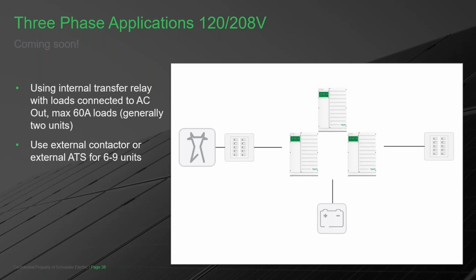So you see master of phase A, master of phase B, and master of phase C. This will keep these inverters at 120 degrees. So they're 120 volts each, and they are 120 degrees from each other. With the difference with 120-240, where the 2 phases, L1 and L2, are 180 degrees from each other, in a 3-phase, the phases are 120. And they'll stay 120 from each other because of the programming. They can connect to a grid, they can export out to a 3-phase grid, they can